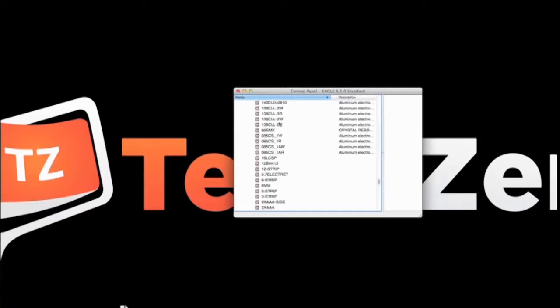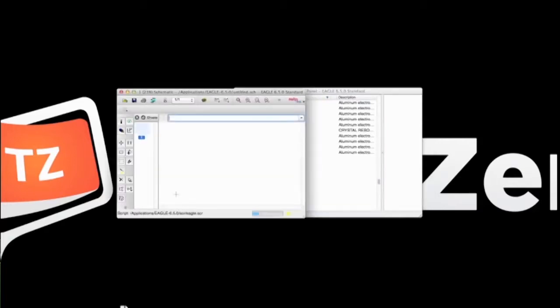But besides the niceties of the libraries and everything, all we want to do right now is create a new schematic. So to do that, it's very simple. You go to File, and you go to New, and you say Schematic, just like that. And we come up with a blank sheet.